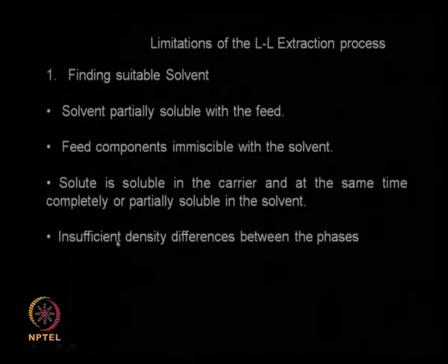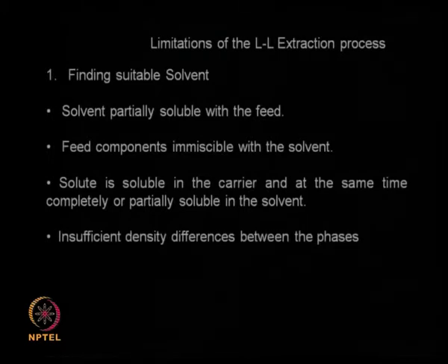If the density differences are not much, then you are not going to get two distinct clear phases. So, these are some of the limitations of liquid extraction. What happens if the solvent is partially soluble in the feed, you are going to lose some solvent.